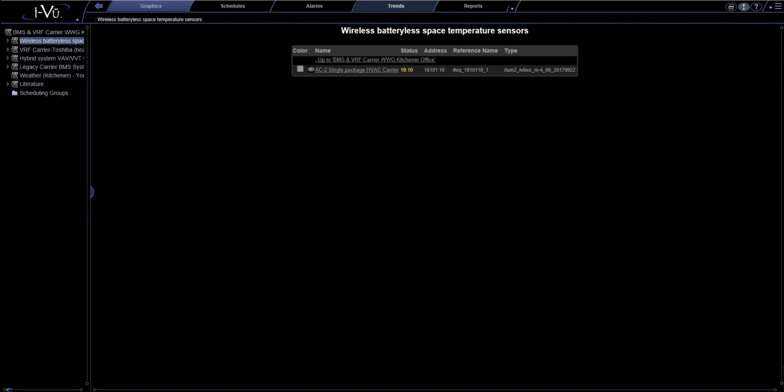retrieve trends of set points such as space temperatures, space humidity, economizer usage that could bring visibility and awareness of potential failures that could cost a lot of money, such as an inoperational economizer when the favorable outdoor conditions would permit usage of the economizer instead of the compressor. We could create reports.